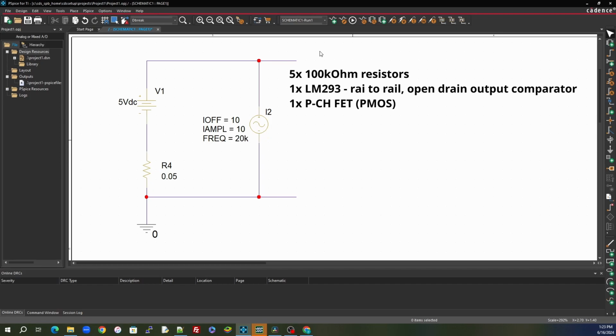Using these 7 components, what circuit can we create that will allow us to keep an output voltage greater than 4.5 volts and basically take the place of that diode? Even though the battery drops due to the motor load, it will not affect our electronic circuit, and it'll keep that side above our 4.5 limit. I'll pause the video here if you would like to try and solve it yourself. Otherwise, I will go over the solution shortly.